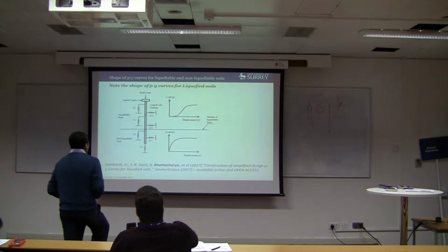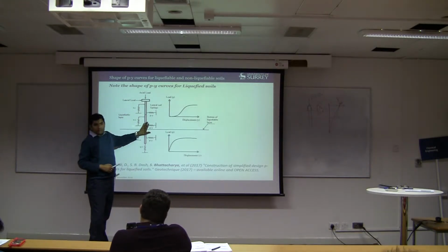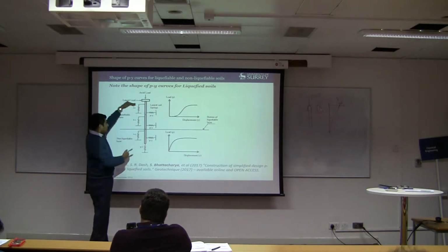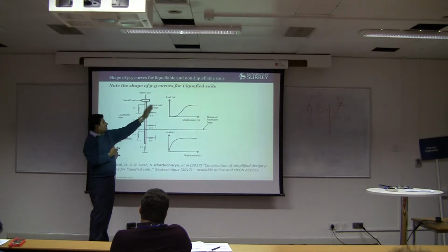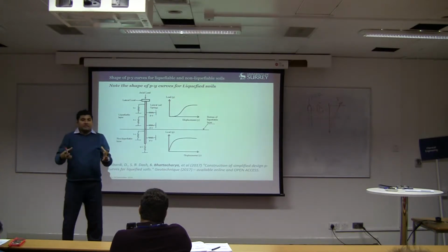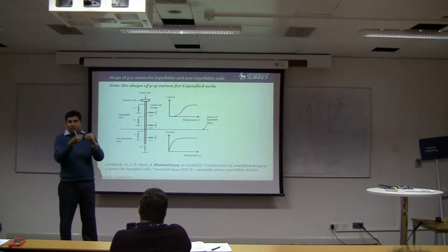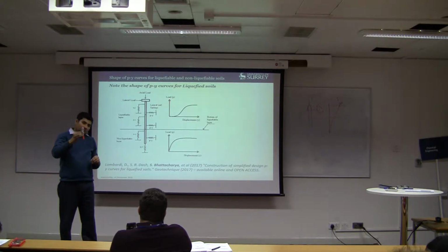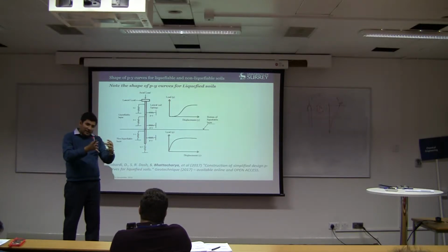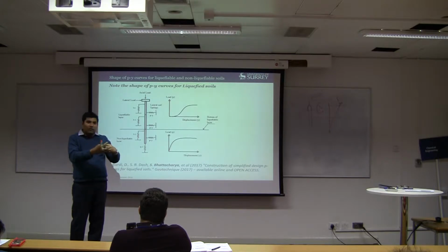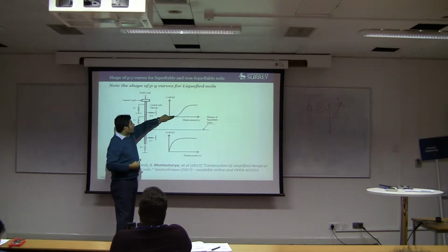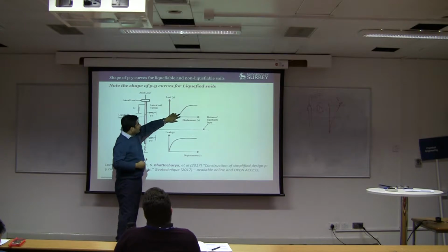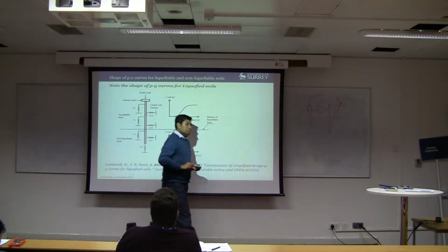The top one, yeah? Okay, say you have a pile here and this is liquefied. This part is liquefied there, this is liquefied. Liquefied means what? Liquefied means that the particles are not in contact. But now if the pile starts to deform, what will happen? Those particles will then gradually come closer and then it forms a lock, but it needs certain movement. This is the no resistance zone. Then it needs more displacement than the other.